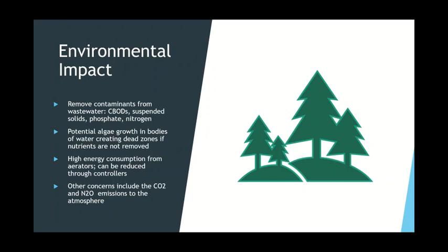The main concern in wastewater treatment is the concentration of CBOD, suspended solids, phosphate, and nitrogen in the effluent. If these values are too high, it can cause algae growth in bodies of water, killing off wildlife and damaging the ecosystem in the body of water where the contaminants are released, creating what is called a dead zone. This is why meeting EPA requirements for these values is very important.